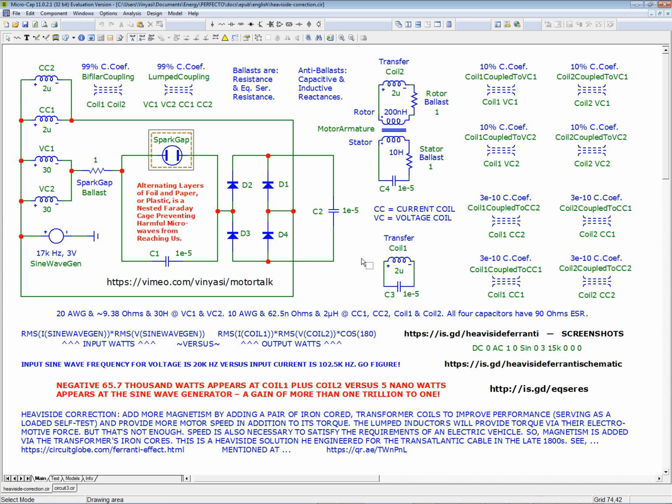Well, whatever it was, it was more than my target, and then less than my target, and I couldn't go in between. Not until I shifted the burden of resistance away from this resistor and into the equivalent series resistance of my 4 capacitors was I able to fine-tune my wattage output. But in so doing, it was at the cost of amperage, and so my volts went up and my amps went down.